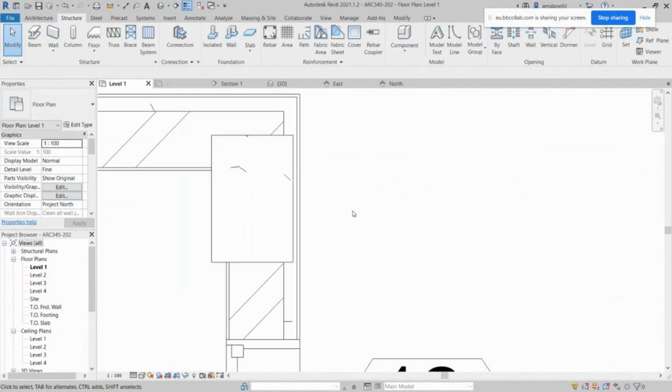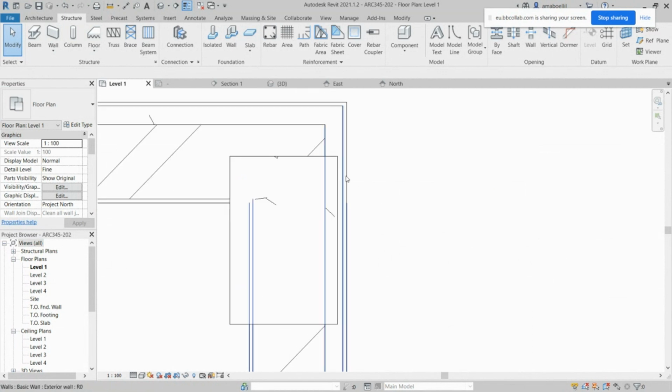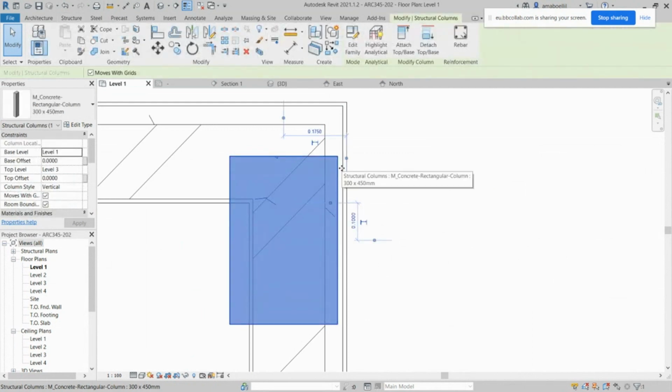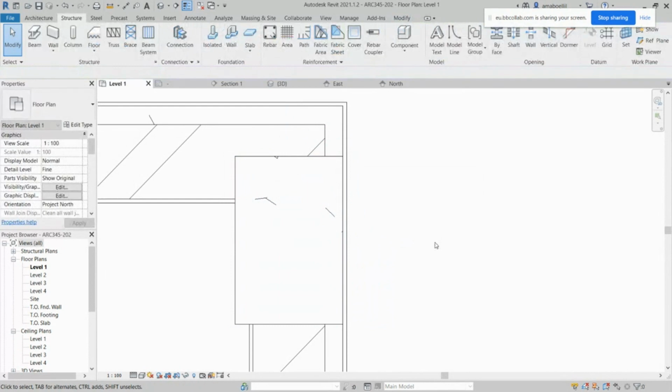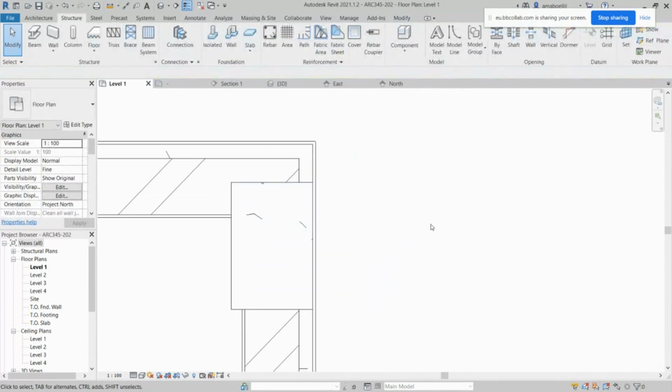Because we are not drafting lines, just an imaginary line. These lines are constructed now. So this thickness compared to this thickness, how it's implemented, sometimes it cannot be done. So it's better to think this out, either to make your door or the column completely flushed, aligned with one wall or one layer, like this. And at the same time, you can adjust the width of it in order to be flush with the other layer. Now, if you are doing a gypsum board layer inside your interior wall, it's ugly to make the column flushed with this gypsum board, because the gypsum board has to be continuous, covering the whole wall.